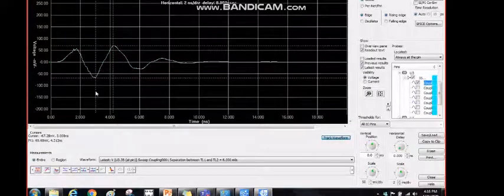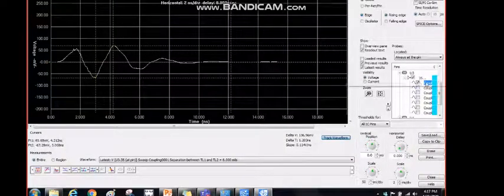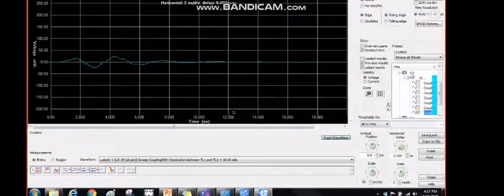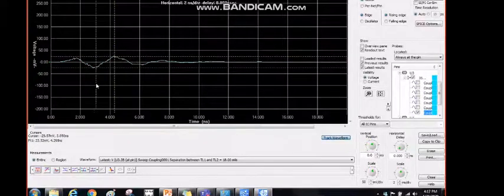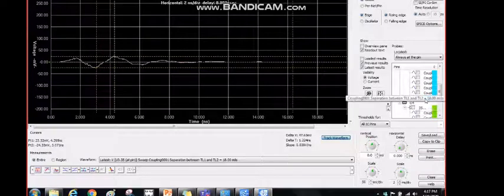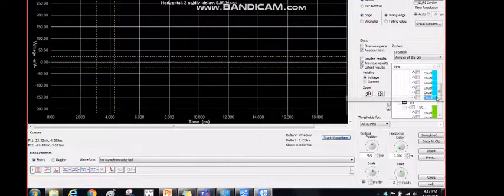So this is close to 137 millivolt at the near end, when the distance between these two transmission lines is 6 mil. And when the distance between the transmission lines is 18 mil, the voltage has significantly reduced to 47.65 millivolt. Same goes for the far end crosstalk.